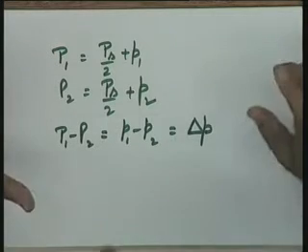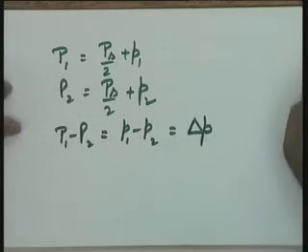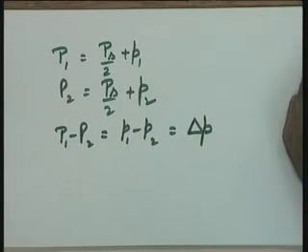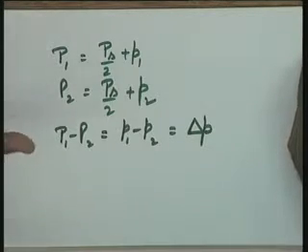Now, this del p is equal to 0 at steady state, please note, and this is the del p which will produce the required force to move the load. After all, what is the force? The force is equal to pressure difference into the area of the piston. So, del p is an important variable, I need your attention on this, because this is the variable which is going to generate the force to move the load.